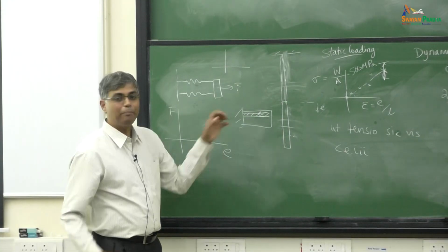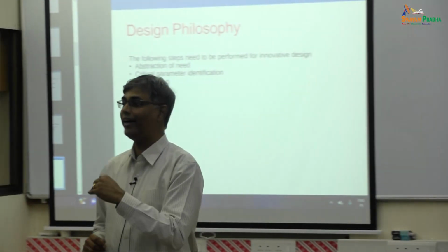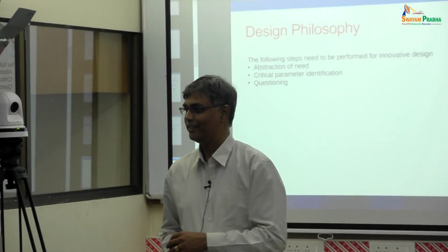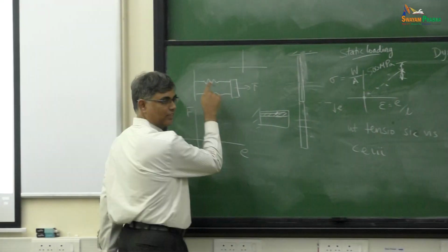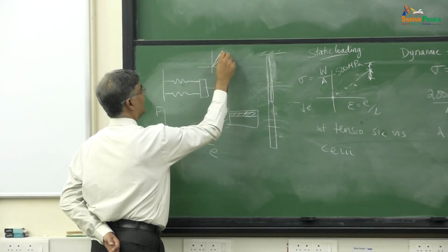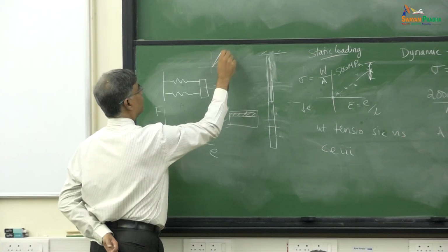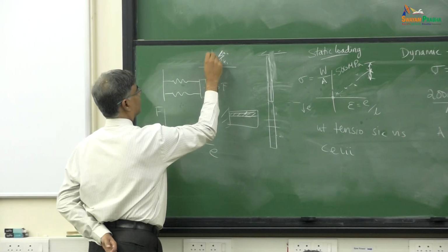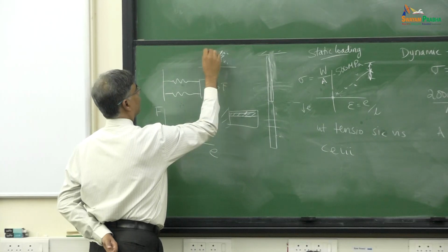So the spring is a bit weaker than the spring where there's no crack. So what I'm saying is, I'm going to model this entire bar as just two springs, but each of these springs will have slightly different K1, K2 and failure strength, failure load F1 and the failure load F2.